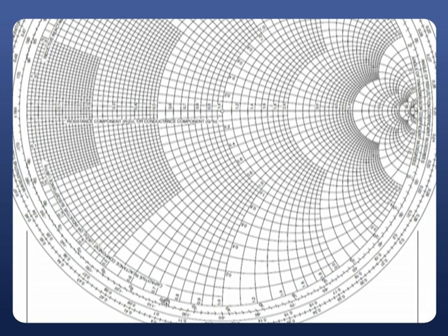How much distance you move and where you have to stop purely depends upon the length of the transmission line. To measure that length, we use the scales around the Smith chart, which are useful for measuring how much we have travelled along the transmission line.